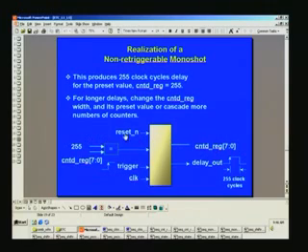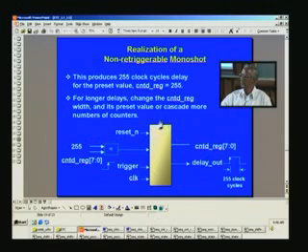So here there's a reset once again, because this is based on a counter, and that counter we call counter D here. D stands for delay, and the output is delay out. You get 2 clock cycles as such, and if you require, you can also see what the counter's present value is. Otherwise, use it internally. All this process triggering will be done at the positive edge, the rising edge of the trigger, and the clock is also there.